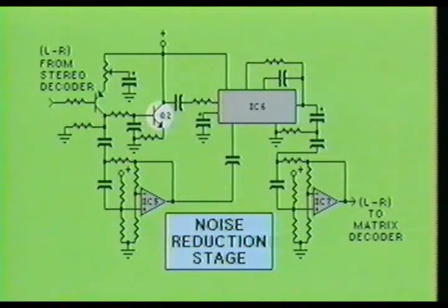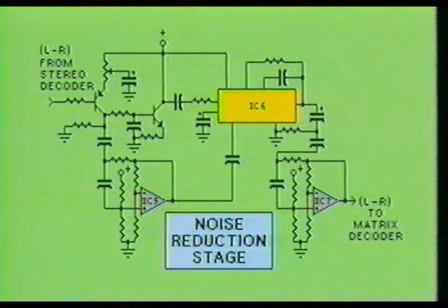The L-R signal splits from transistor Q1 and goes to transistor Q2 and IC5. Transistor Q2 reinverts the L-R signal for one of the inputs of IC6. IC5 provides a high-pass filter for the other input of IC6. This high-pass filter helps to eliminate any vertical sync buzz which may be present in the L-R audio signal. IC6 is used as a 2-to-1 audio expander for the L-R signal. IC6 simply doubles the amplitude of the L-R signal based on its frequency content.